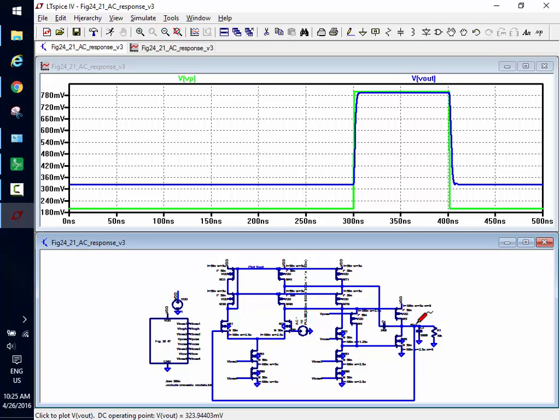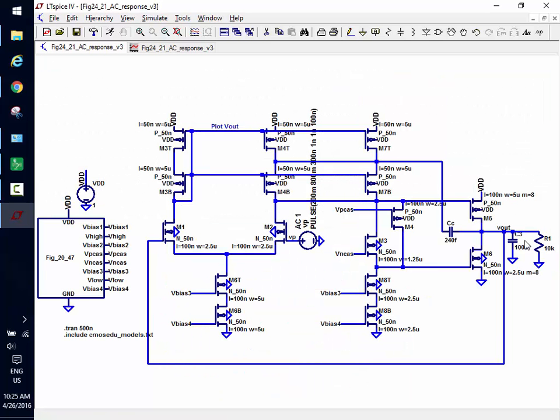Does everybody see that? So would it make sense to do your input from 0 to 5 volts, and then your output running 80% of your input? See, the input here, let's make sure we understand. You might ask, why do we need this op amp? What does it do? This load that I have here, which is an ideal voltage source, when you drive the op amp, it takes zero current, right? So if your source had a high impedance, it could drive the op amp and then the op amp would drive the load.